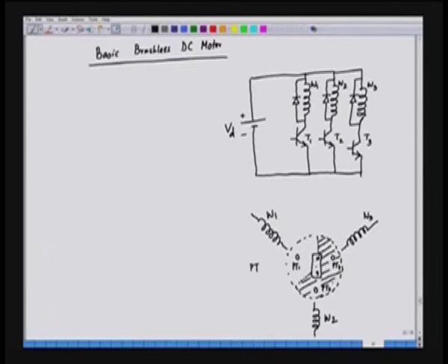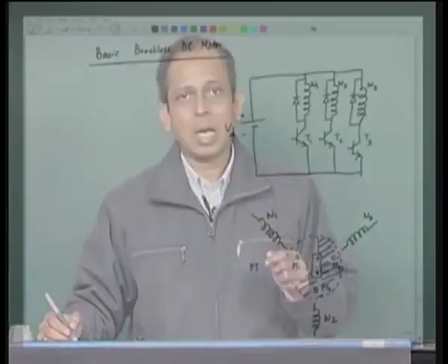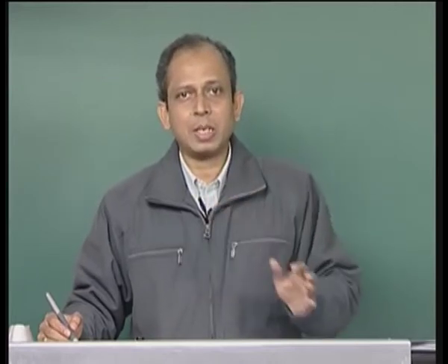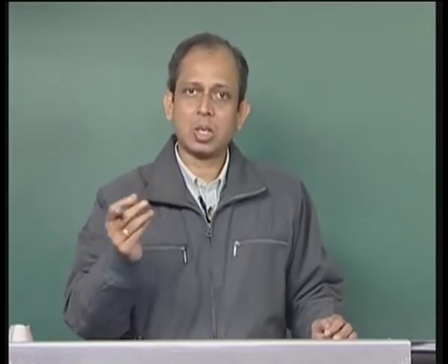So, this hashed region is basically the shorter or the opaque region, and the region which is clean is the transparent region. So, we have 3 phototransistors, and on the other side we have the photo source. Whenever the opaque region is encountered, the phototransistor does not give any signal, or the signal is 0, and when the transparent region is encountered, the light passes, and the corresponding phototransistor will give a high signal or a 1 signal.